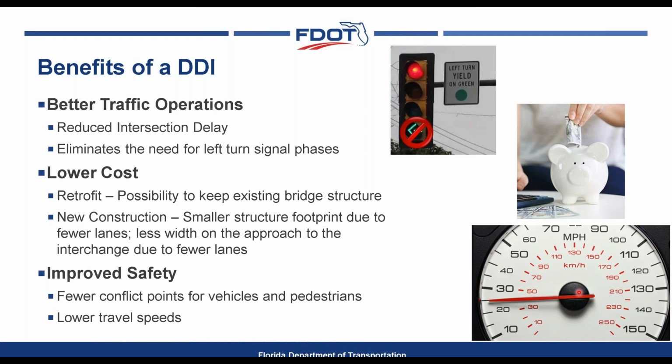And then finally, the DDI improves the safety at the interchange. There are fewer conflict points, reduced congestion, and lower travel speeds through the crossover intersections result in fewer crashes in the corridor.